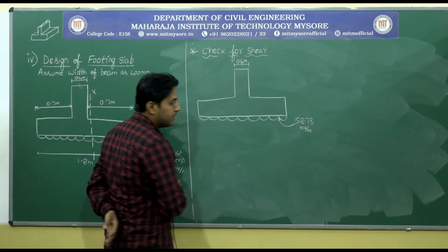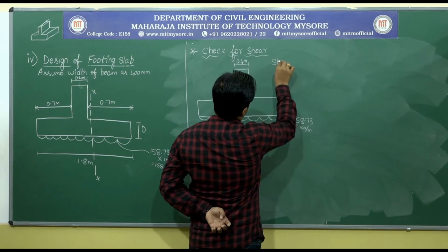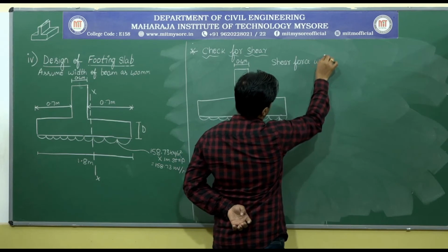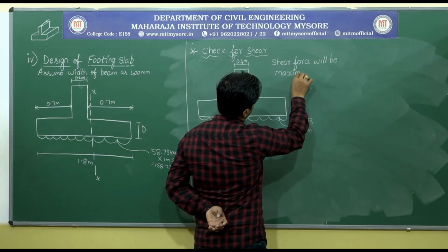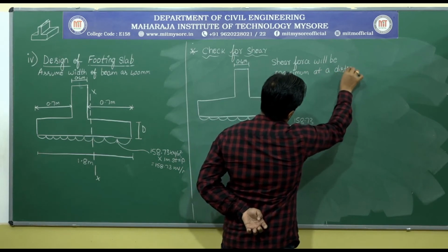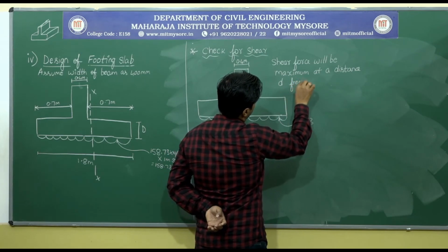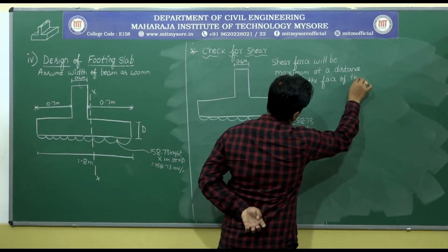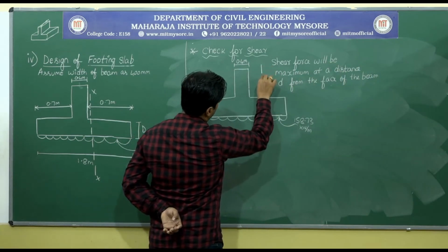So that's why what we will be writing here, shear force will be maximum at a distance d from the face of the beam. So please remember this. So from the face of the beam, let me draw a section.